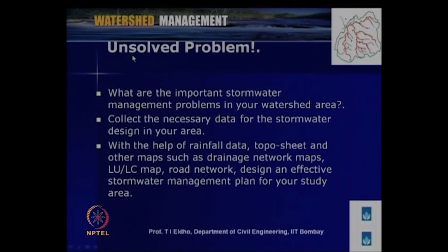Before closing down, one unsolved problem: what are the important stormwater management problems in your watershed area? Collect the necessary data for the stormwater design in your area with the help of rainfall data, topo sheets and other maps such as drainage network maps, land use land cover map, and road network, and design an effective stormwater management plan for your study area. As presented in the case study, you can come up with a typical design to deal with the stormwater management issues.